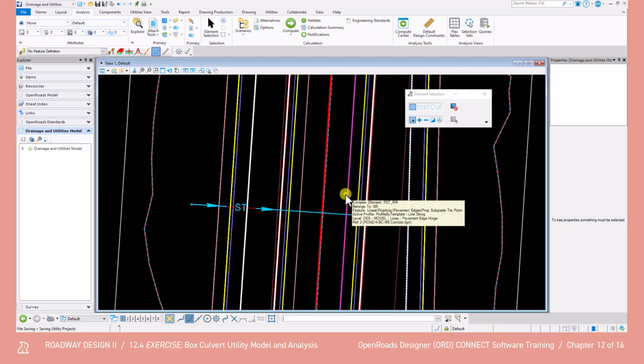So from STD 17-11, we will need some of the dimensions. So note, for scenarios requiring at least 1 foot of embedment per Chapter 6 of the TDOT Drainage Manual, ensure that the proposed box culvert and wing wall heights account for this embedment. Likewise, the proposed inverts need to be adjusted 1 foot down from the hydraulic inverts to place the box correctly. So from that standard drawing, we need to know that H, or fill height, is 10 foot, the wall length, or W, is 18.5 feet, and the wall height, or H, is 6.5 feet.